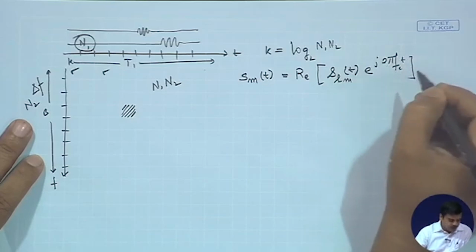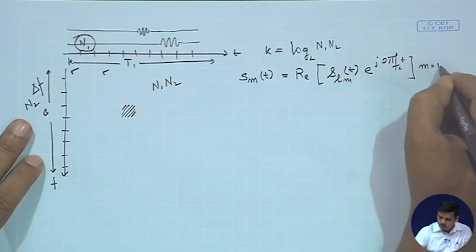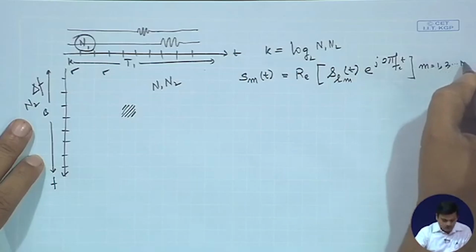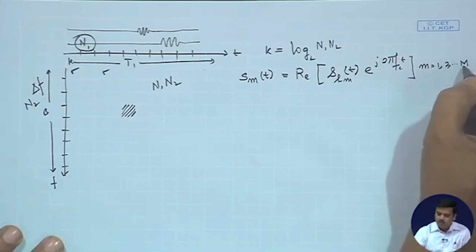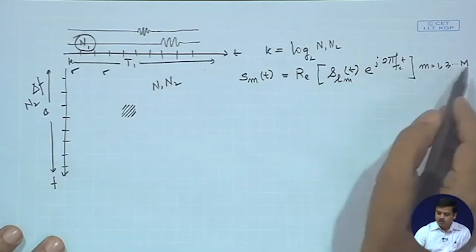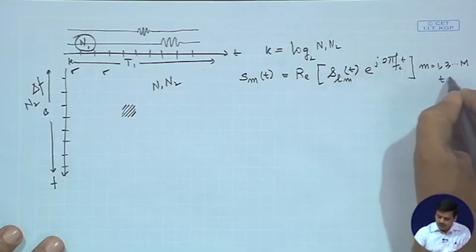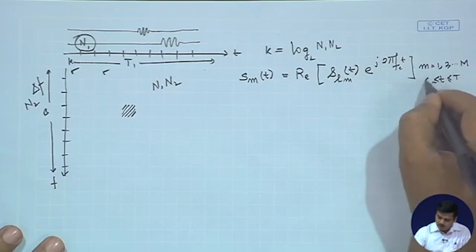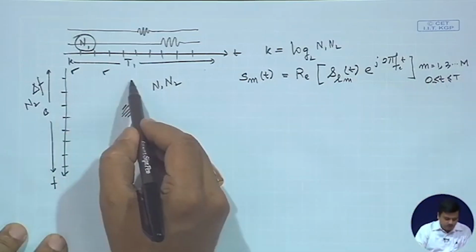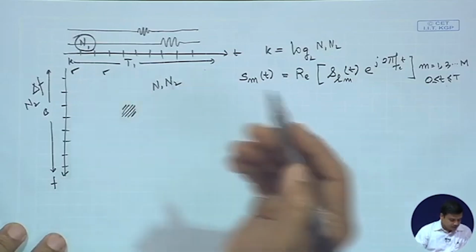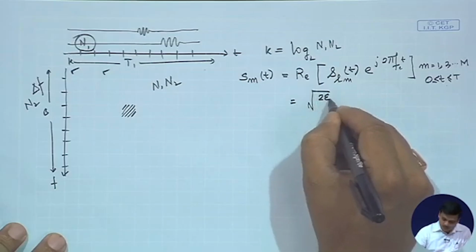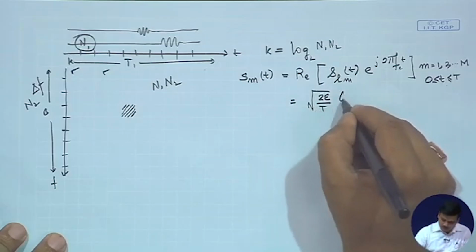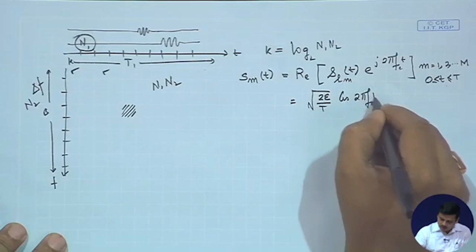Now, this is a standard form, of course, m equals 1, 2 up to capital M. So, here when I write m, I mean M possible options. I have used N1 and N2, this M could be any one of them, and it is valid for t less than or equal to T, being 0 otherwise. So, any one particular section could have this, and you could easily write it as the square root of 2E, that is the energy, upon T, times cos 2 pi f_c t.